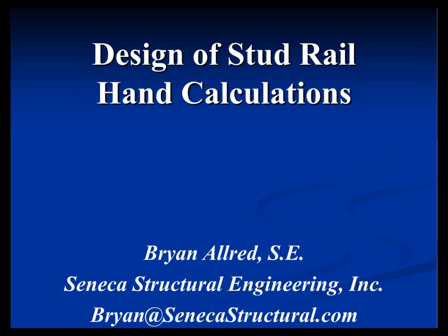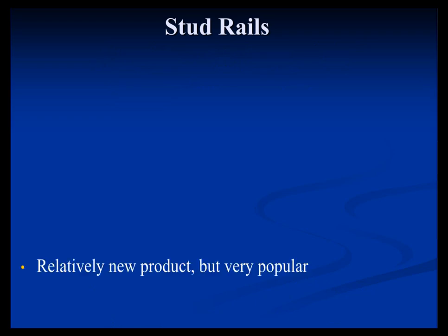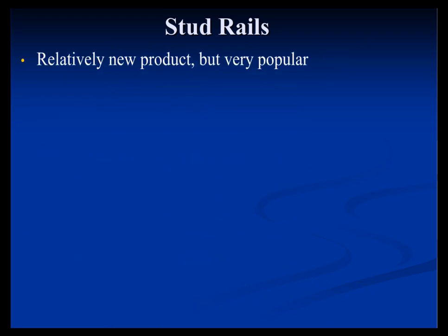They work equally well in both, but considering they're relatively new in the reinforced concrete realm, if you compare that relative to concrete, PT, or rebar, which has been around for a number of years, stud rails for punching shear are a relatively new system. With that said, there's not a tremendous amount of documentation that I'm aware of. I could be wrong. I didn't do a huge literature search, but in textbooks for Concrete 101 courses in college or even advanced in graduate school, I don't believe there's a tremendous amount of documentation on how to actually design the stud rails or the numerics involved and stuff like that.